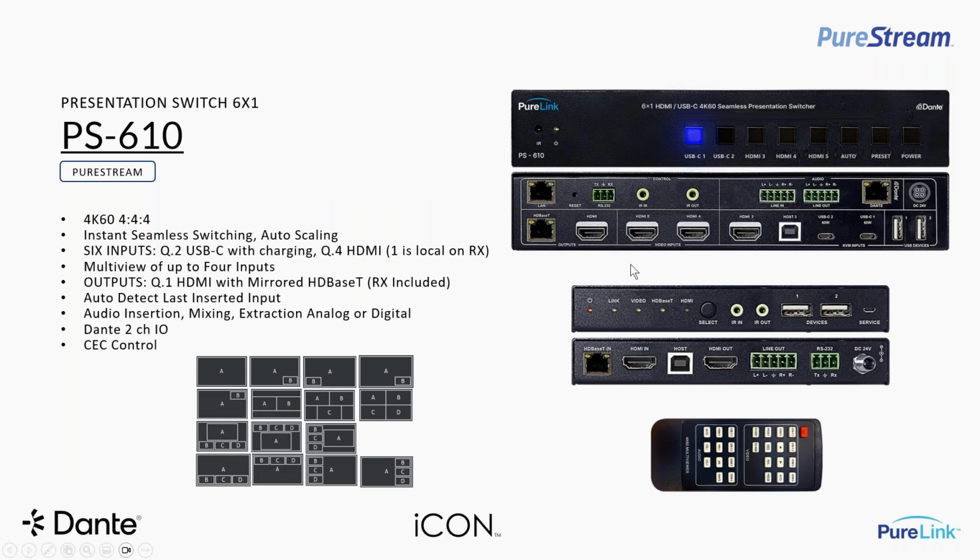So I can bring 2 channels of audio in from the Dante network into the PS610 out to the outputs, HDMI or HD-BaseT. And I can also take the output bus 2-channel audio into the Dante network.